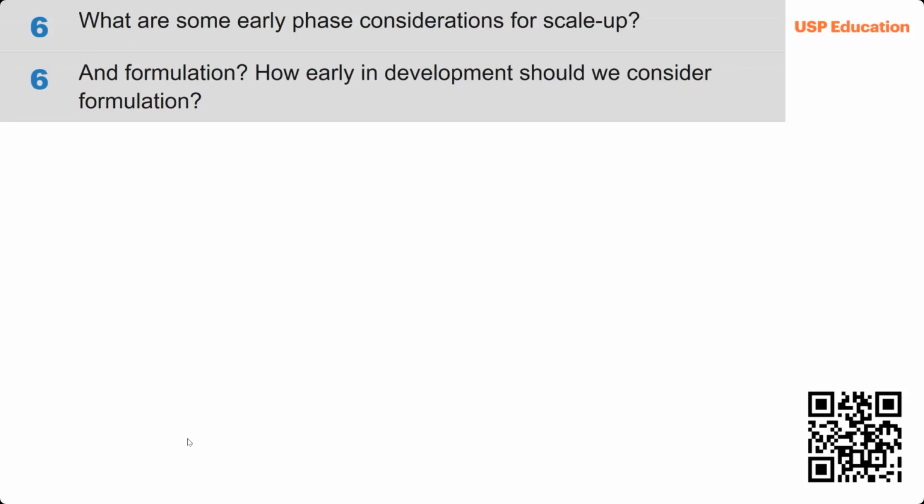A lot of vendors these days will offer quite a bit of characterization data on their bioreactor systems. It's really important to understand the shear forces generated at the impeller tip, and the overall considerations for dissolving air into the culture, to make sure the cells are getting what they need, they're as productive as possible, and you're getting to the optical densities you need to get the right antibody titer.